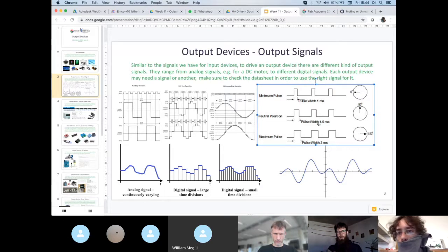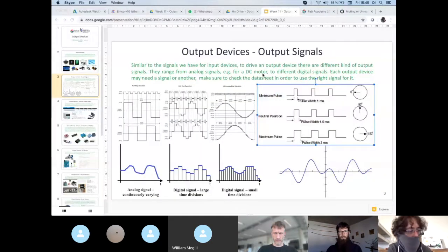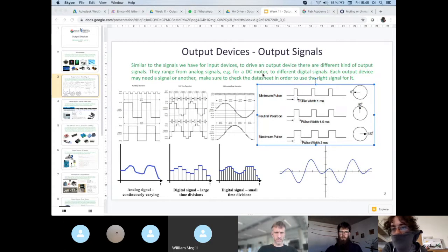This is some kind of standard that works in almost all motor controllers, a standard for all the producers of motor controllers. If the pulse is 1 millisecond, the motor stands still, and if the pulse is 2 milliseconds, it spins at the full RPM. But not for DC motors, because with DC motors you need to use a transistor, and then this depends on the characteristics of the transistor. I'm talking about brushless motors in this case, and servo motors.